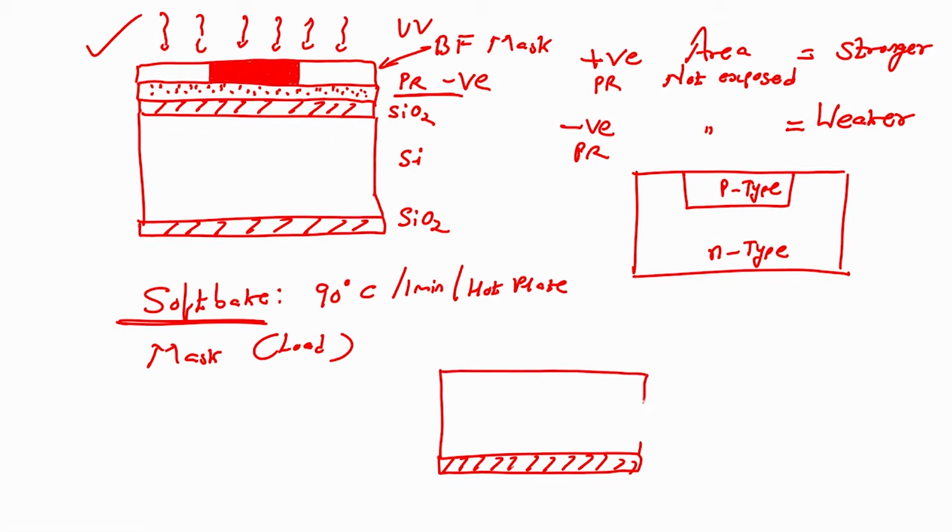We will find that the photoresist which is not exposed, so I have to develop it, right. Photoresist which was not exposed got weaker and got developed. Photoresist that was not exposed, right. So, photoresist which is below this area will not be exposed and it got weaker, and then it got developed in the photoresist developer, correct.